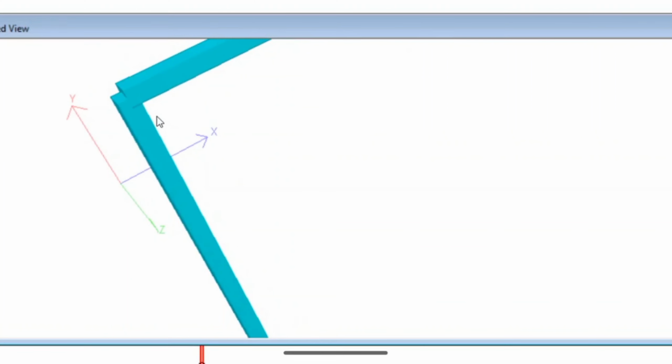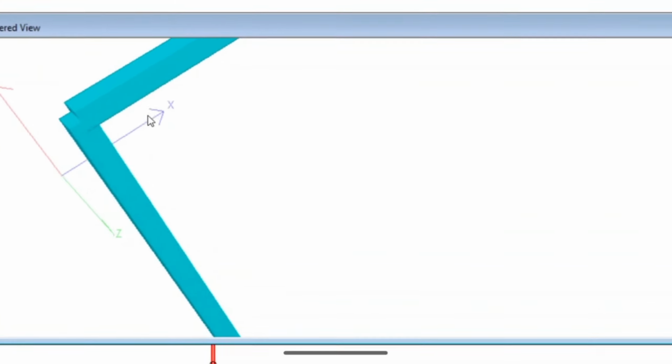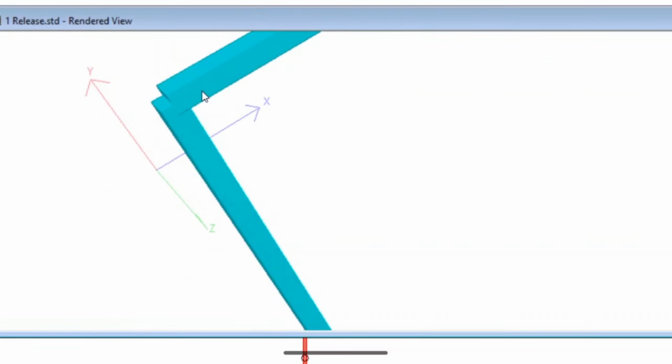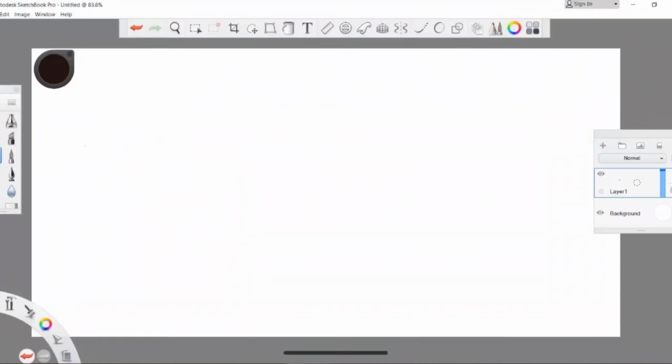then you can see how they have been connected. You can see that the beam has gone into the column up to half of its width, and there is a small gap between the column and the beam portion over here. The column should have gone up to the top of the beam, but it hasn't gone. In reality what happens is that in the beam column junction, it doesn't happen like that is shown in the STAAD Pro. In reality what happens is,